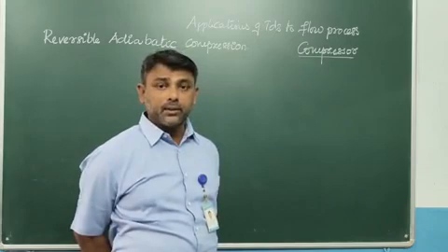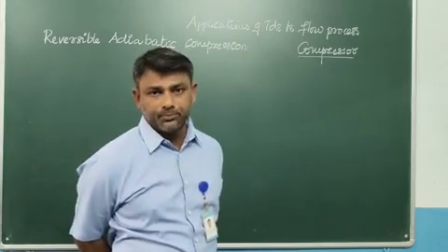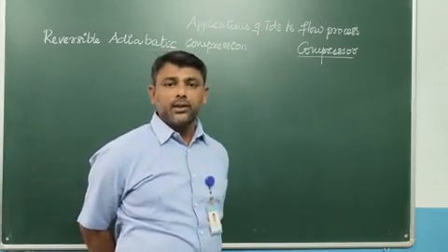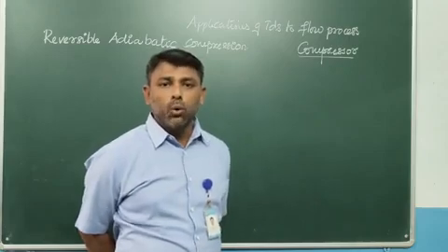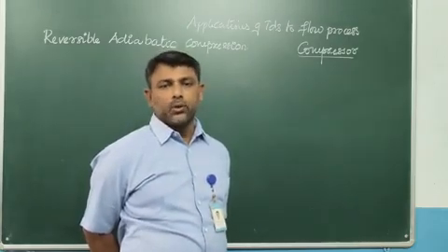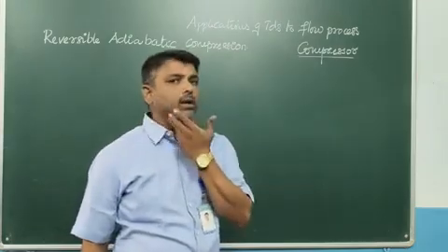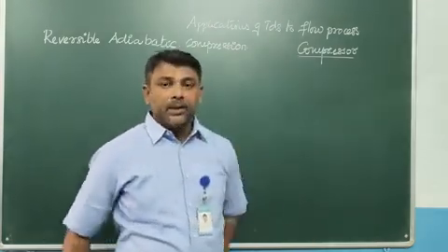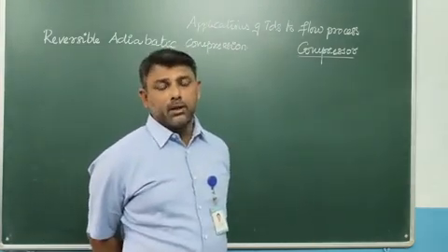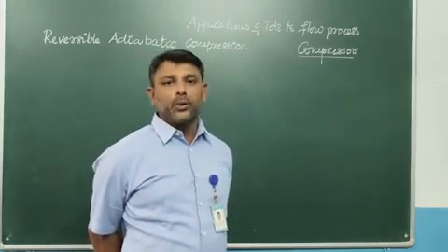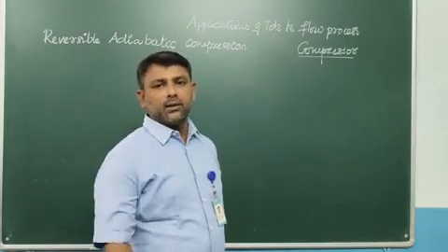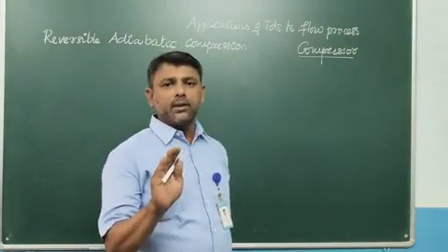Reciprocating type compressors are used for high pressure, but unfortunately they provide low volumetric flow rate. While turbo type or centrifugal type compressors give high volumetric flow rate, unfortunately they provide low pressure. Clear?